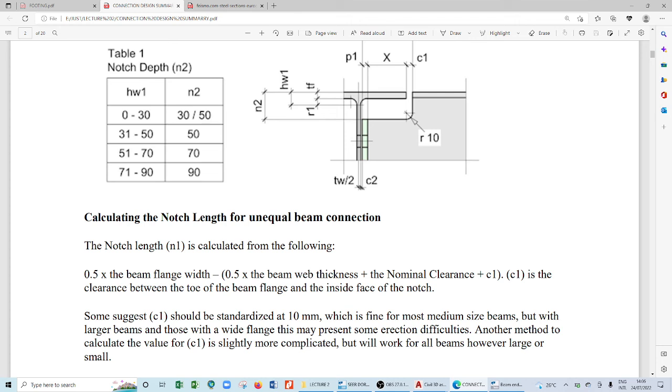They are not sharp angles. It's a curve, a nice curve. So it is that radius. We are trying to clear it so that it comes to this flat part. This is also a flat end, then it will sit nicely, and you can weld the two here. If it came and touched here, the lower part will not touch. Are we together? If you cut it too short, you have a gap here. You're trying to avoid that gap.